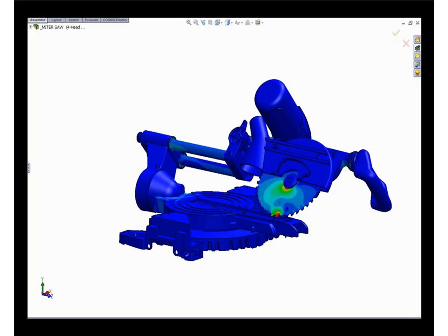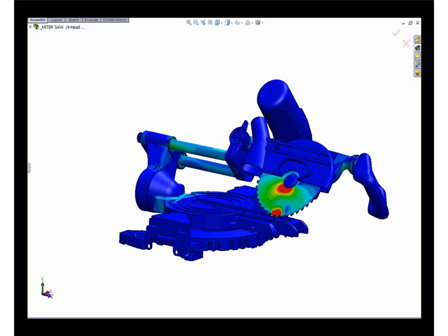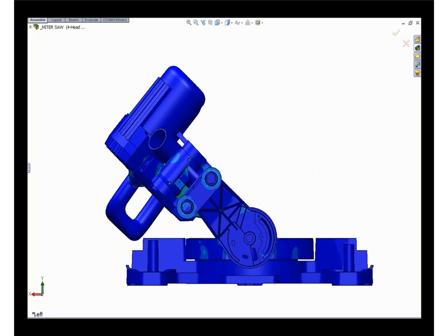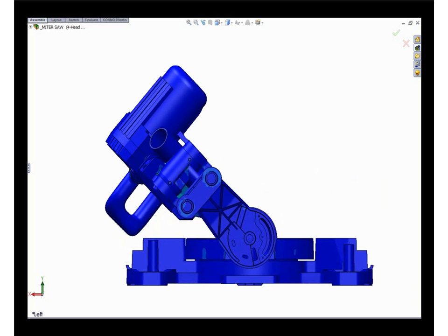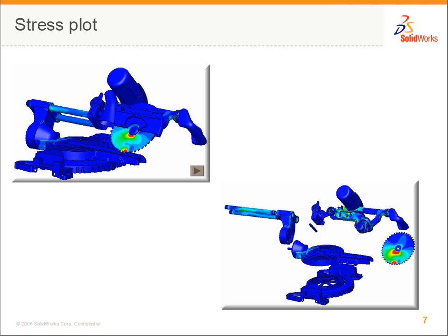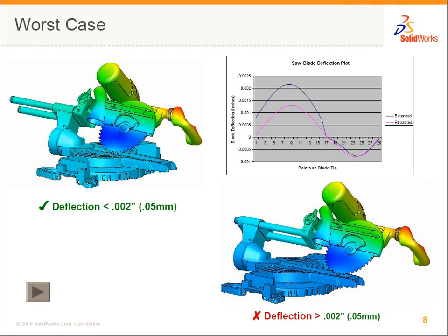The 3D interface allows us to interrogate the model from any angle. And here we see that the saw blades do see a lot of stress, but the linear slides and pedestal also have considerable amounts of stress and contribute to the deflection. So right away, Cosmos has given us great insight into our design's performance.